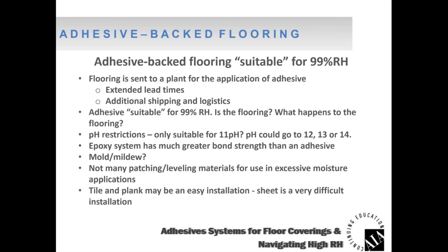Adhesive back flooring: tile and plank is an easy installation. It's just like a peel and stick, drop it in place. If you're considering a sheet installation, that's a little bit more difficult. So I would say if you're considering that, play around with it, get comfortable with the installation before you tackle one, because there's certainly going to be a learning curve with the installation.